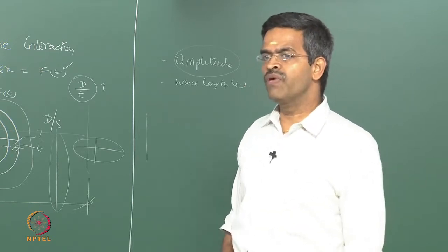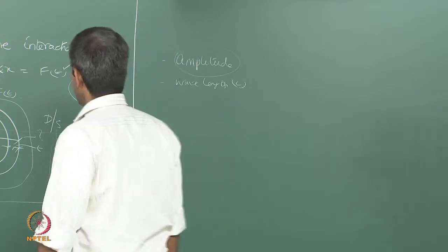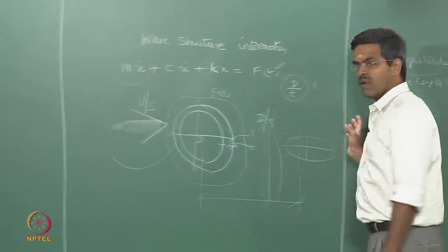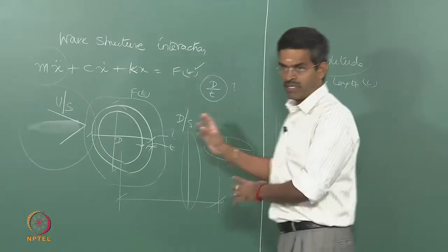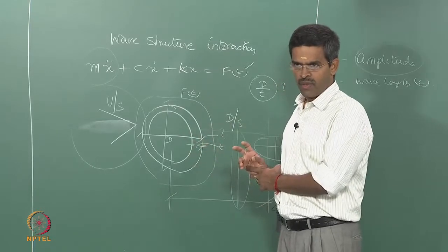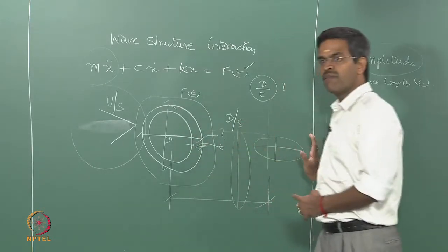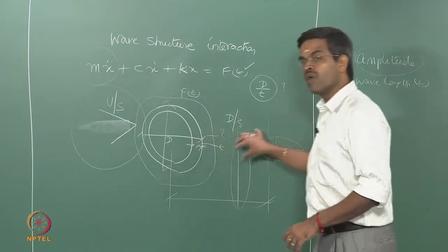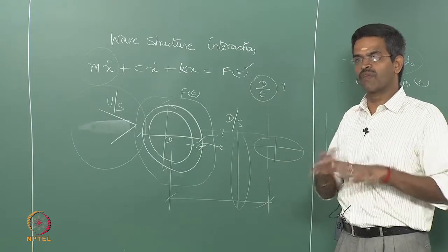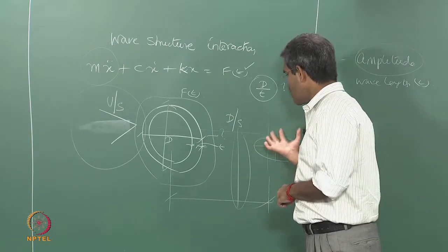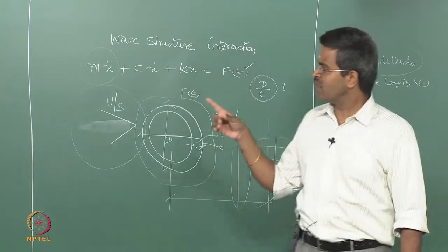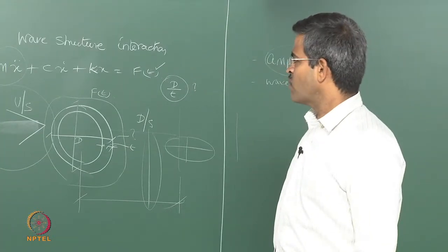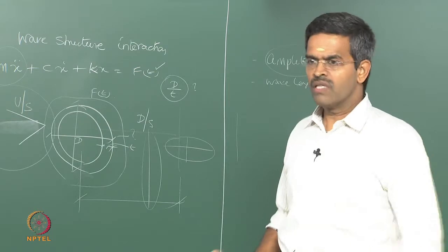Now, there is something called the far field flow condition. What it means is that the body is located here, this is my incident wave field, and this is my downstream far field. Now, what is the influence of the far field on the body? Will it reflect back on the member? Will I have any interference on the successive member nearby, depending upon the spacing of the members? I have to capture this also, because if I have successive members in one row, what we call a group or cluster of cylinders, then the interference effect on this member will come back on this member also. So, I must always classify my far field boundary condition, or flow condition, which states that the flow at infinity is only an outgoing flow. That is a general assumption.